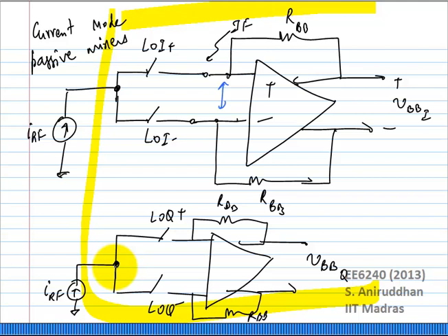The important thing to note is that obviously the noise will get translated in frequency. The second thing is you will have to keep track of correlations. If you try to separate the outputs, for example, into Y1 of F and Y2 of F, the noise going through the two paths could be correlated. So you'll have to keep track of that. Okay. So we will stop now and continue that next class.